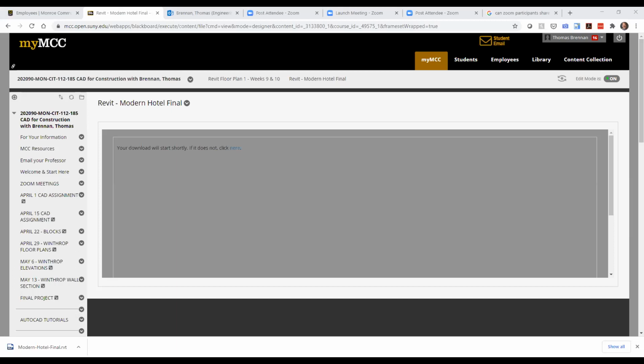Okay, Shane, you got that too, right? Yes. So what you've got going on right now is a modern hotel. Let me show you a couple things here. First of all, you can zoom in and out by just using the wheel on your mouse. Roll your mouse forward and you zoom in, roll it back towards you and you zoom out. That's how you zoom in and out, the same way you did in AutoCAD. So just go ahead and practice that.